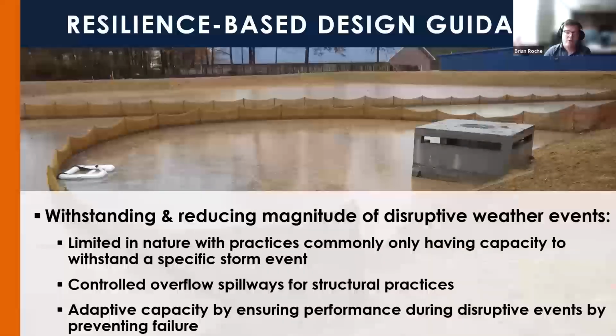We did find, though, that overflow spillways can be used for structural practices, such as sediment basins, other stormwater retention practices, or ditch checks, that allow for withstanding of that disruptive event, while also increasing adaptive capacity by ensuring that these practices don't fail during these disruptive events.